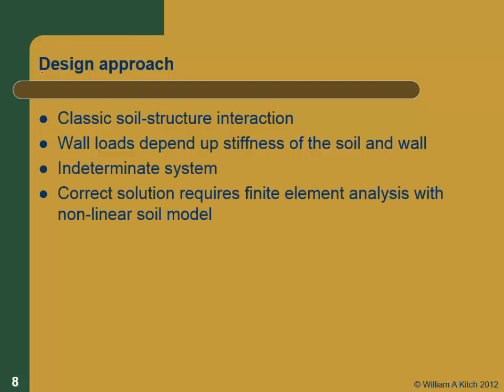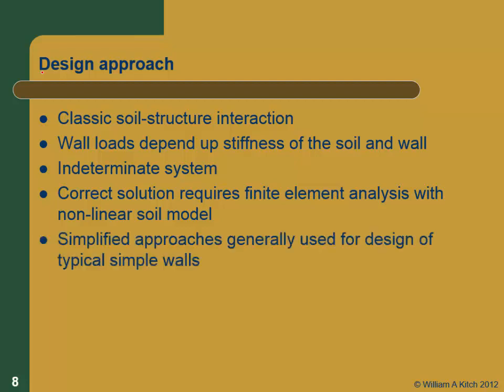So in order to get a complete solution to this, just like any indeterminate system, we're going to have to use load displacement mechanisms, or we're going to have to know the stress strain properties of both the soil and the wall. So that means we're going to have to run a finite element program with nonlinear soil models, which we can do. But there are several simplified approaches that we can take to do this, and that's what we're going to go over today.